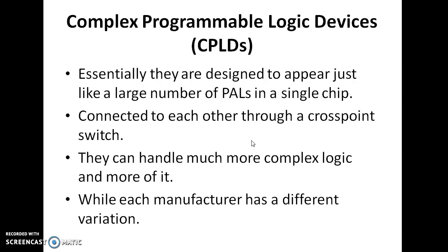So complex programmable logic device means CPLDs. Essentially they are designed by combining PALs. So many number of PALs are combined to form a single chip. That means you can realize complex functions using CPLDs because you are combining so many PALs. All the PALs are connected through a cross point switch. So they can handle complex logic functions, and it varies according to the manufacturer.